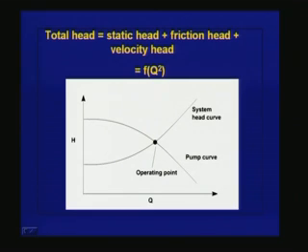From this one can find out what is the pump head developed, and one can take the flow from the pump and then put it through a discharge measuring device and find out what is the flow coming out of the pump during the pump test, and one can plot this head developed by the pump as a function of this Q.